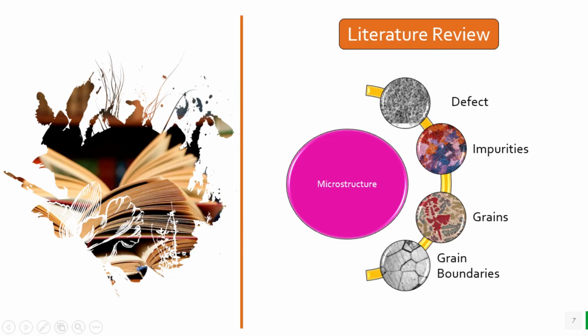Okay, examples of the microstructure are defects, impurities, grains, and grain boundaries. A defect is a general or simple error or interruption in the uniform crystalline lattice, while impurities are atoms like dirt that don't belong in a regular crystalline structure. Then the grains are pure crystal or uniform sections of crystal growth. And lastly, grain boundaries are the boundaries around the separate grains.